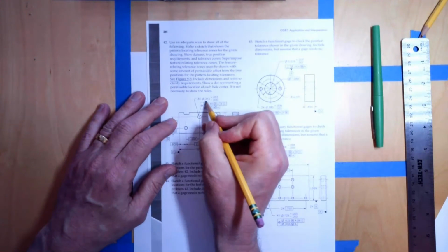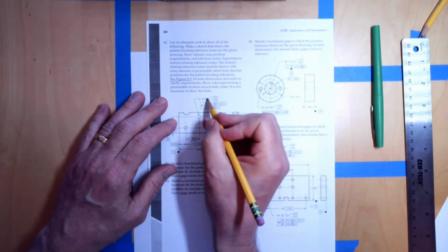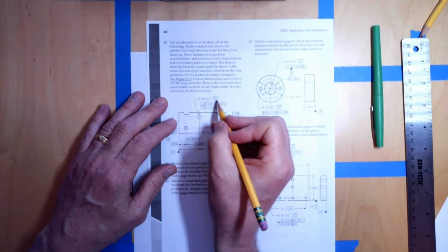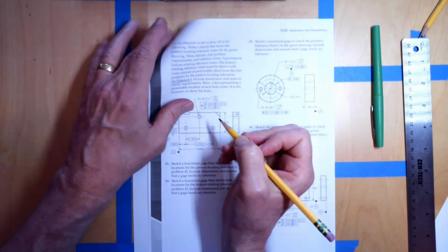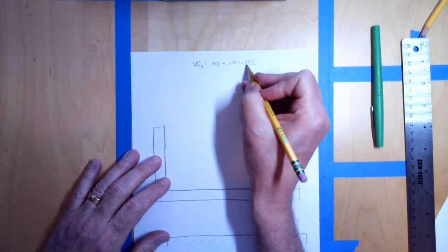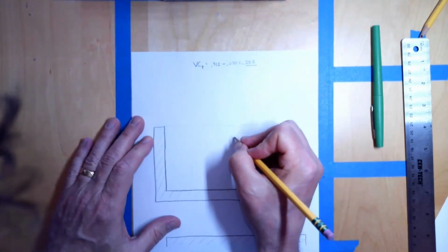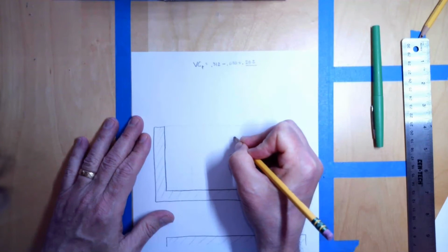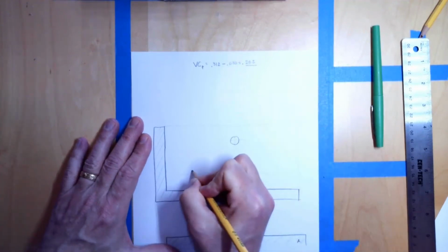Okay, again, just to show you where I got that from, .312 minus 0 is the MMC of the hole, and then .030 is the tolerance. All right, so that's the normal virtual condition equation. So I get a virtual condition size of the pin of .282. And so that's what I'm going to have, 3 pins that are going to be of a size of .282 right here.